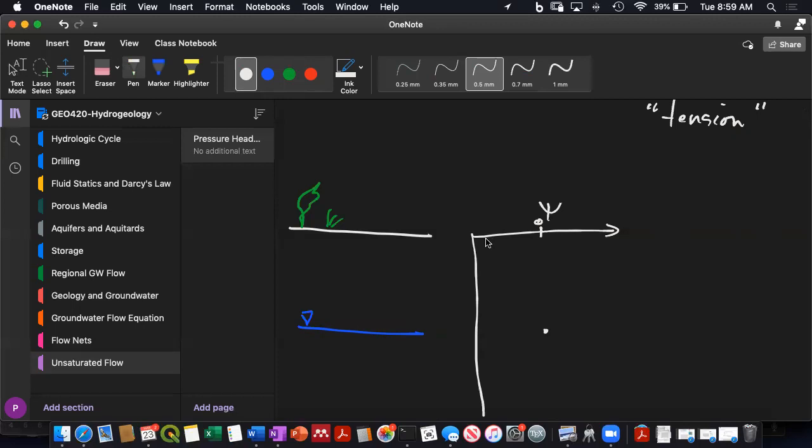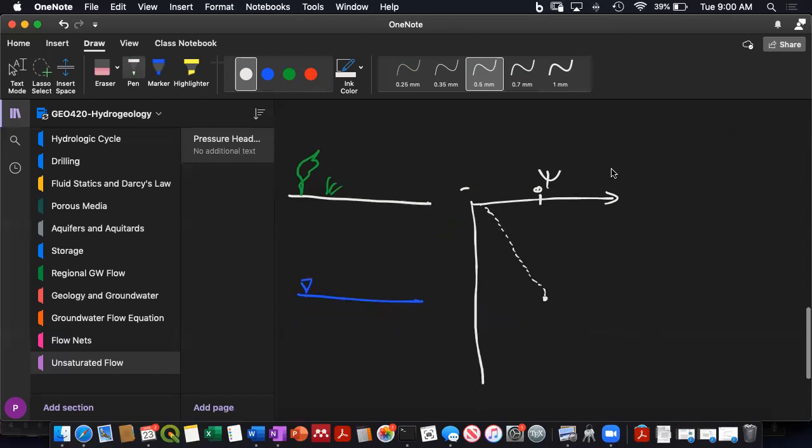All right. Below that, my pressure head is negative. Or sorry, above that, my pressure head is negative. So in the vadose zone, my pressure head is negative. And once I reach the water table and I start moving down, my pressure head increases with the height. So the water table is the zone where I move from negative pressure head to positive pressure head.